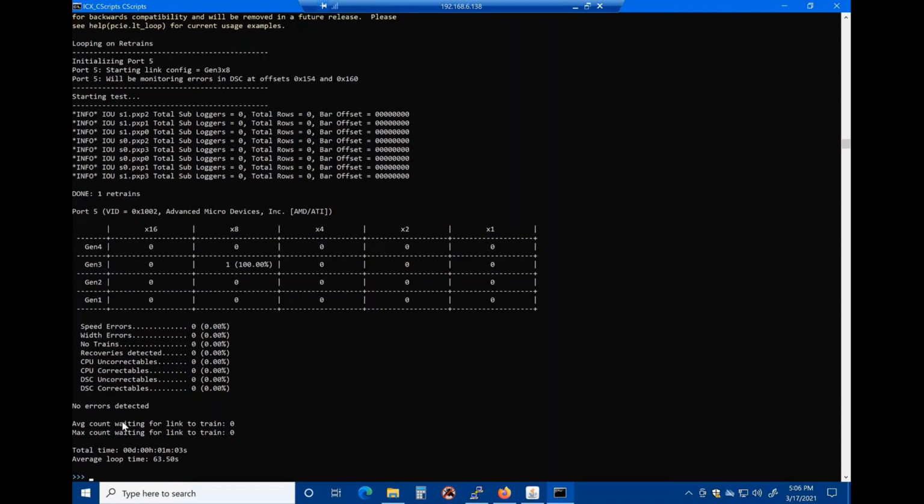So this is what you probably wouldn't want to do in production too much, just because of the amount of time involved. You really want to run hundreds, thousands, 10,000 loops to really stress the link and look for those intermittent bit errors. And we'll see the solution to that now, after we do the crash dump C script and turn our attention to the on-target diagnostics.